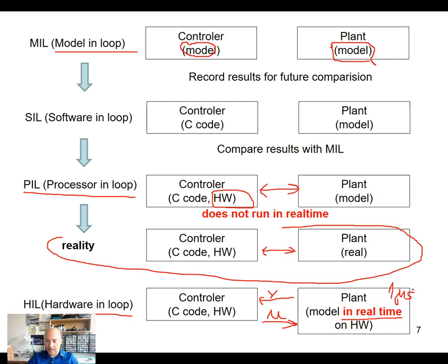So if this is the sampling rate, 1 microsecond of my system, then if I have a controller that has, let's say, 100 milliseconds reaction, then it would definitely not be suitable to control this plant. So if it should run in real time, the delay that you create in the control algorithm should be much smaller than you have in the plant. So in our systems that we will study here, we will need to change the properties of the model.